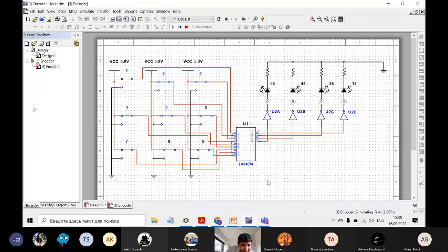Okay, so now my switches are all closed. So actually to each input, I apply 1, with high voltage. Next, for example, I push this button 2. In this position I apply 5 volts, but when I push, I apply 0. So actually it is designed in such a way that you activate not by high value, you activate by low value.